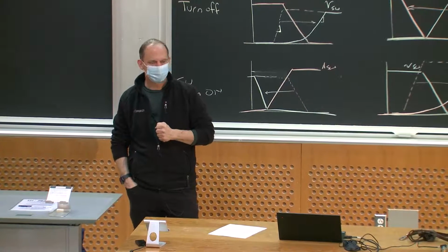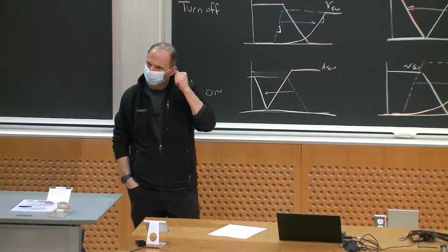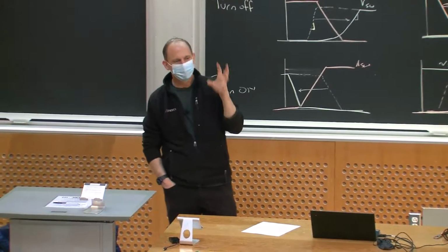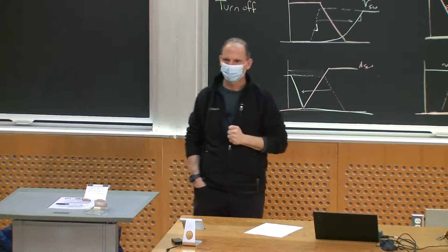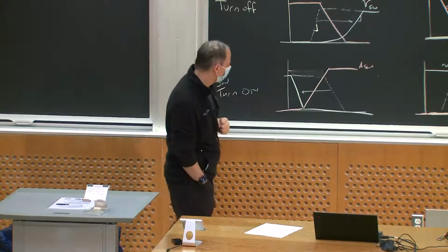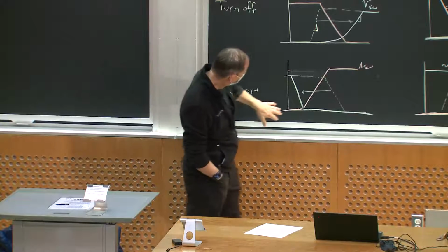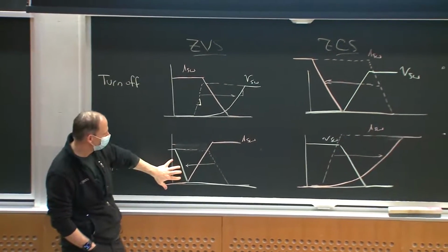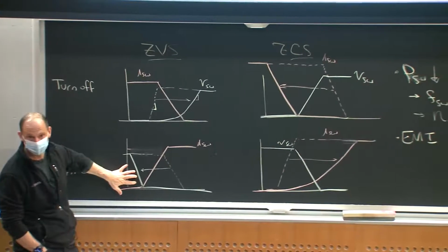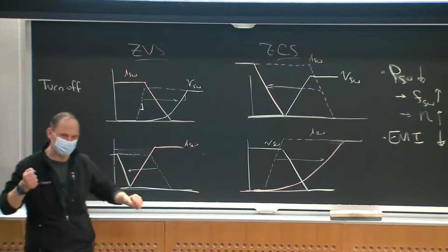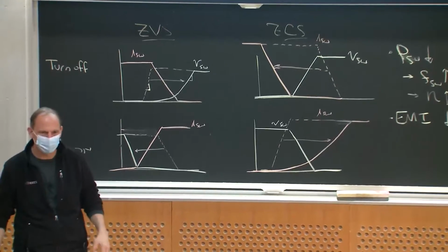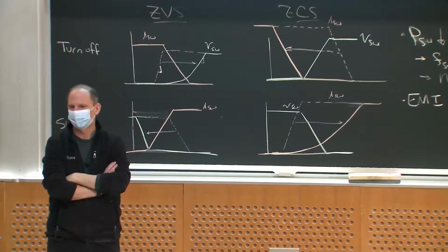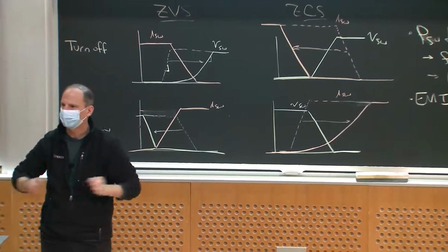And that usually means that the way the circuit's component values are chosen, the whole control scheme, everything is geared around meeting the requirements of soft switching. Why? Because maybe I have to make the circuit do something magic, and I only want to turn the switch on when the voltage is already 0 across the switch. So that prevents me from just doing standard fixed frequency PWM. So that's one very broad category of circuits.